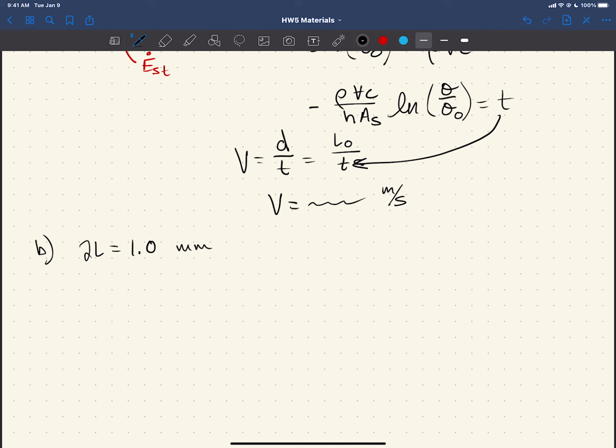You guys probably have an intuitive or common sense understanding that that's the case, and if not, the math that we do here can show it, but I'm not going to do that. And so your buddy's like, all right, we can bump up the conveyor velocity if we use thinner ones and still get the same results. And if the conveyor velocity is bumped up, then we're going to be putting out more cereal flakes. So with all that being said, I'm done blabbing. Basically, you go back and you do the same problem, except now your thickness is 1 millimeter instead of 1.2 millimeters, and you do all the same work that we did above, and then you get a new velocity, and you check, is it greater or not? And I mean, it should be.